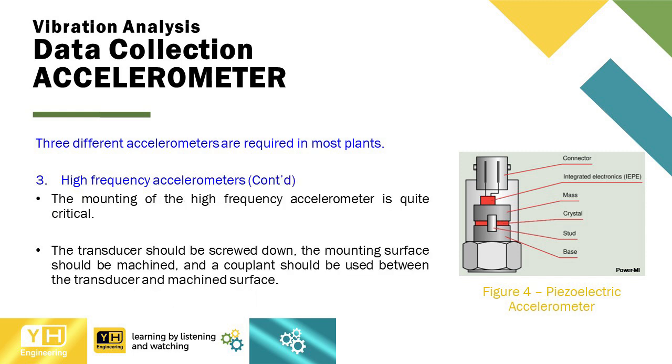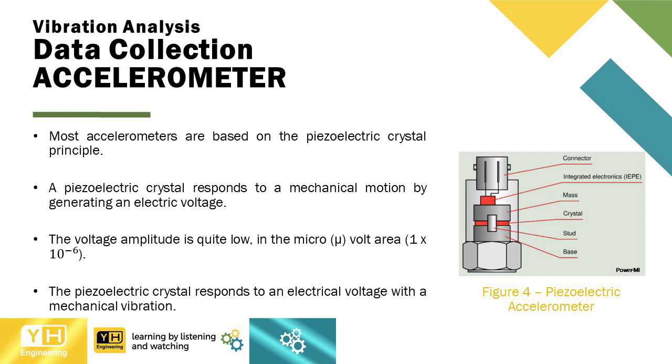The mounting of the high-frequency accelerometer is quite critical. The transducer should be screwed down, the mounting surface should be machined, and a couplant should be used between the transducer and machine surface. Most accelerometers are based on the piezoelectric crystal principle.